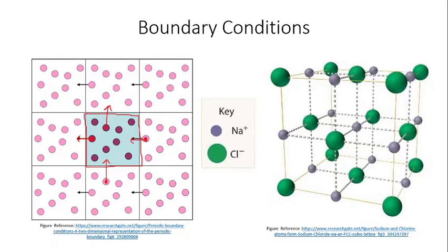Now the F, which is the fixed boundary. Suppose this is the X direction and this is the Y direction. Now if you consider that this Y boundary is fixed, then what happens? F means the position of the face is fixed, and if an atom moves outside the face, it will be deleted on the next time step that reneighboring occurs.